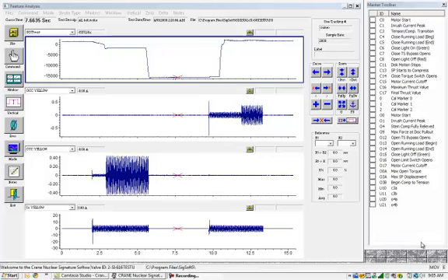Alright, well, here we go. I'm just going to mark, as you can see on my screen here, I've got the analysis screen a little bit smaller, and I put up the marker toolbar so you can just carry along with what I'm talking about here. So first thing I'm going to do is zero my thrust trace. Not in particular order, but the things you need to do first are zero your torque, thrust, spring pack, and do your 0 times.